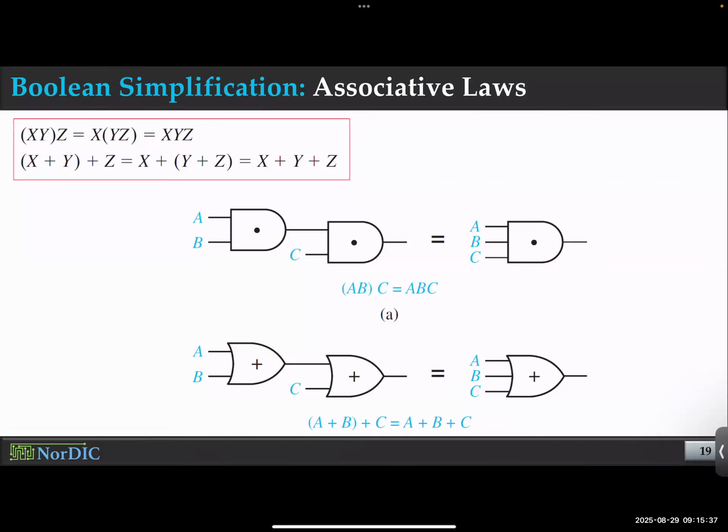Or you could make it more complicated, meaning, hey, I want to optimize everything. It shouldn't have too much area or be too slow or have too high a power. So that means it's a trifold optimization, more complicated. And there are other factors that we have to optimize for, which I'm not getting into here, right? These are called setup time constraints, hold time constraints. So you add constraints to the design method.